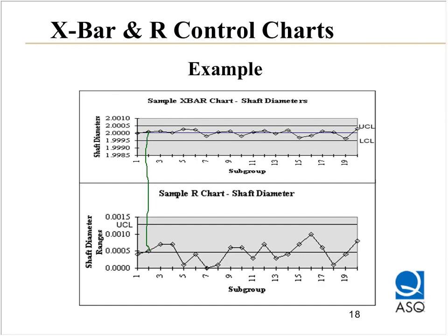In later years, a lot of people have moved from the R value to the S value, the standard deviation, because we now have considerably greater facility in calculating variation using the standard deviation than back in the days when the X bar and R chart was first devised.